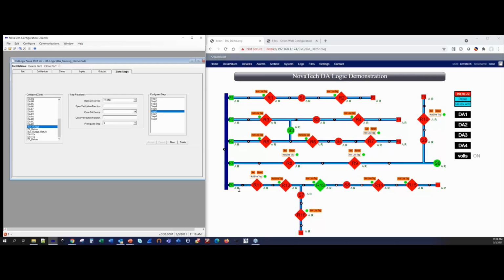The reason is that we can't bridge everything that was tied together down to feeder F10, so we have to make some of that load isolated for a while and then bridge that later. So we are going to open up here, followed by, when this is complete, then we're going to close switch 8. And also, when this is confirmed, because that's what step 6 is, we're going to close switch 7.